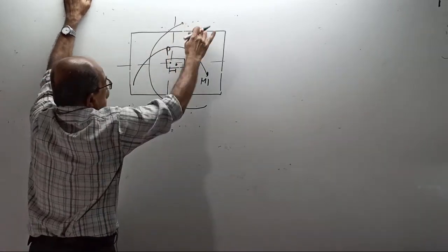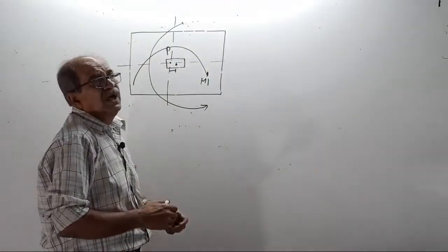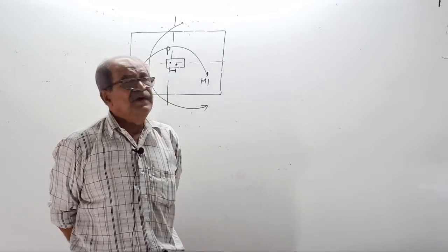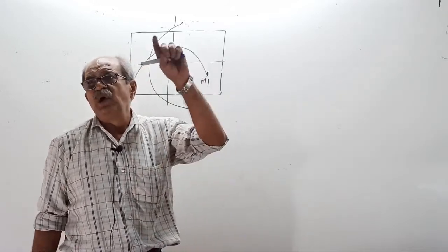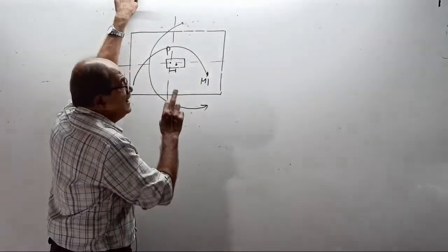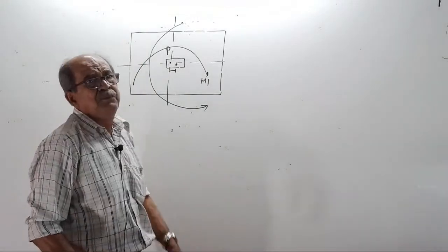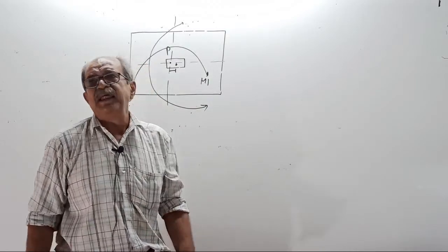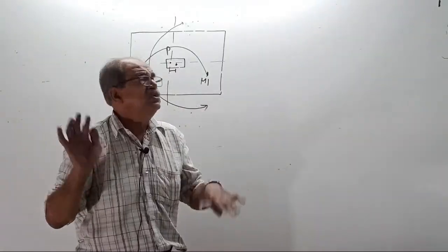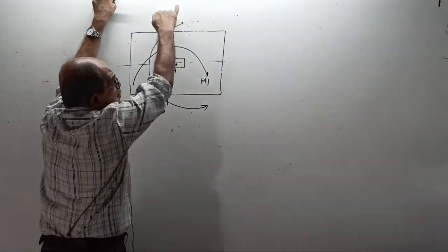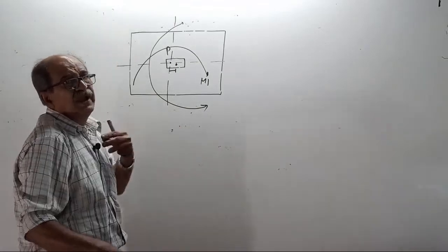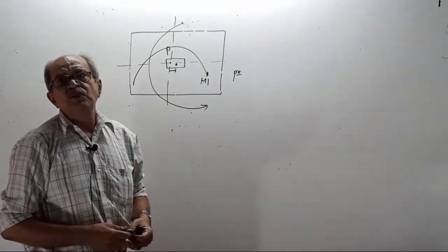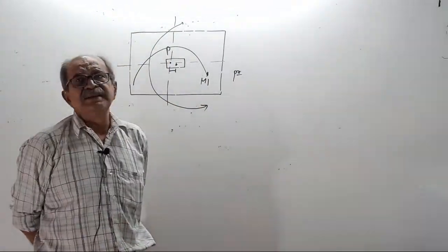Actually, it will come this way. Okay, no problem. So it will become a case of axial load with M1, M2 once again. Make a note: the design principle will be the same as what you are going to cover from now onwards, the design of a column footing when the column is transferring axial load with M1, M2. I can't call every time one moment this way. M1 is lengthwise, M2 is widthwise. It can be this way, no problem. Then the pressure variation will not be uniform. It will be non-uniform, and we consider linear variation.